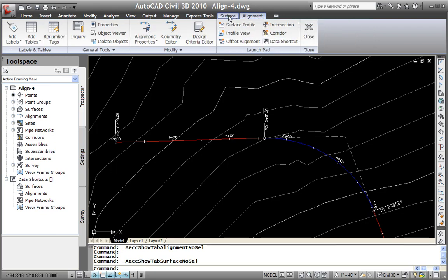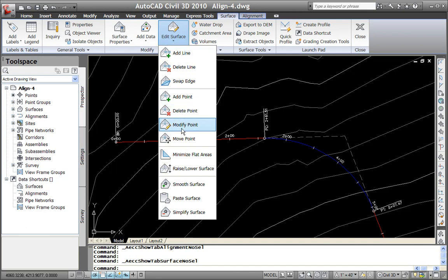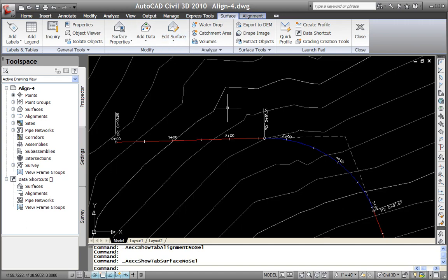So now what I do is I toggle back and forth between the command. So I don't select an object because that gives me the other tab. Here I select the command first. So I have a surface and I want to edit the surface. And then once I select the command, it'll ask me to pick the surface that I want to apply the command to. So you can see that's the main distinction between those green tabs, which is when we select the object first, the noun-verb selection, and these purplish bluish tabs where I select the command or the verb and then work with the objects. So if you want to work on a number of objects at the same time, you'd probably want to open these tabs. And if you're just quickly editing a specific object, then you just go ahead and click it. It's a quick and dirty procedure and you're off and running.